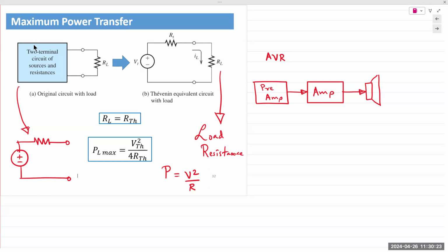That's not how it equals. It's a condition that must be met in order for maximum power to be transferred. So there is a small derivation. Typically, we don't do it for non-E major classes, but we derive the equation and then we set it to derive PL max. When we set it to derive PL max, the result is that RL equals RTH. So the result of that derivation gives us RL equals RTH. Good question. The question being asked was, how is it RL plus RTH?